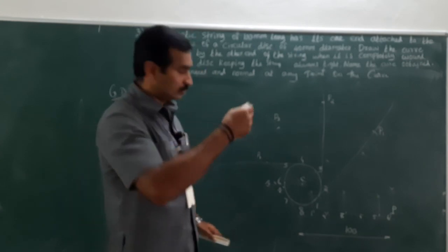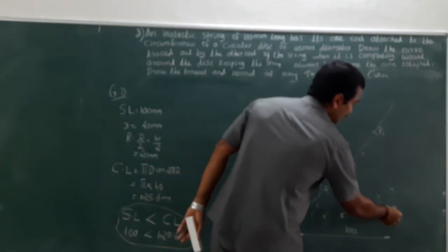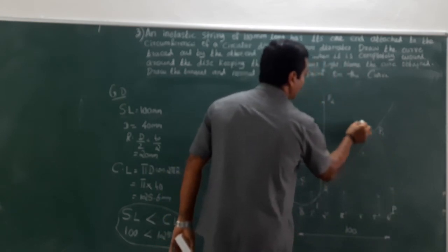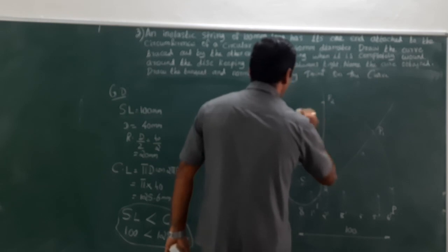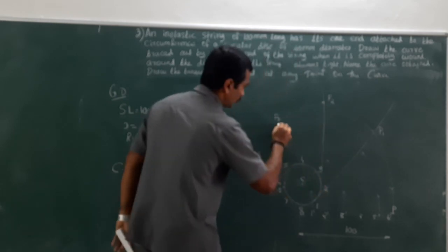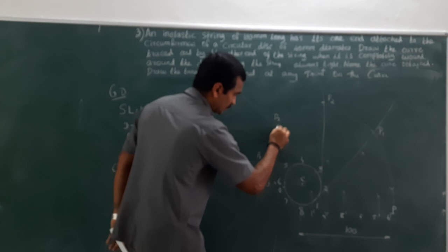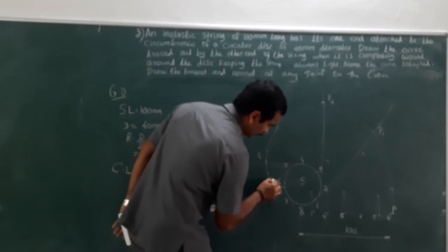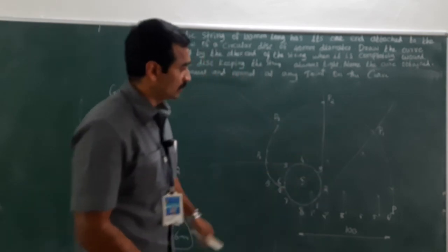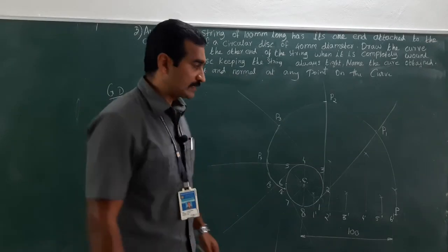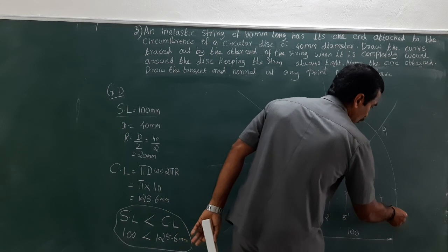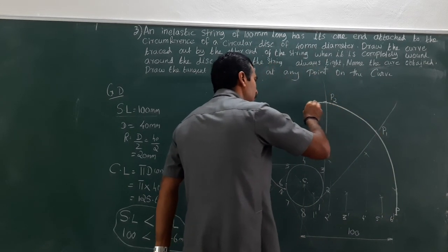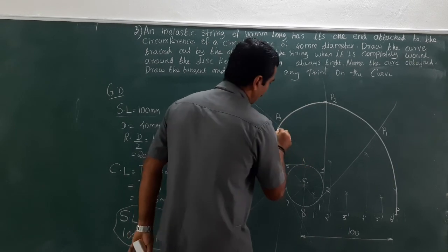Now I need to plot the points by smooth curve, by freehand, passing through all the points. Draw the curve as smooth as possible. Right? What is next? Now change the pencil to H or HB, and draw a dark line on the profile.